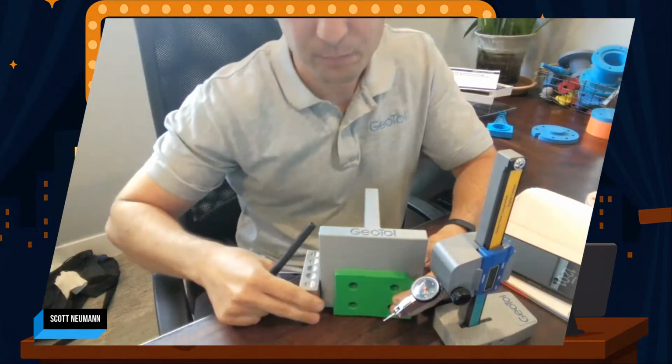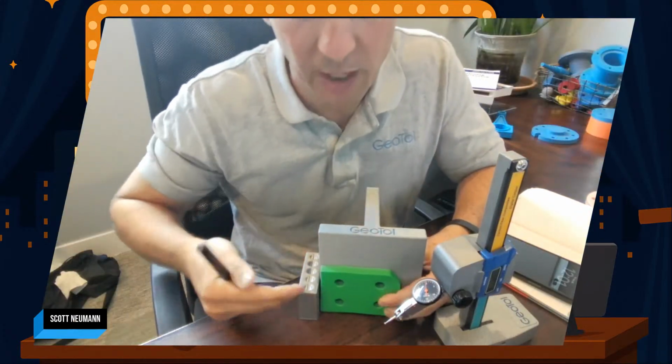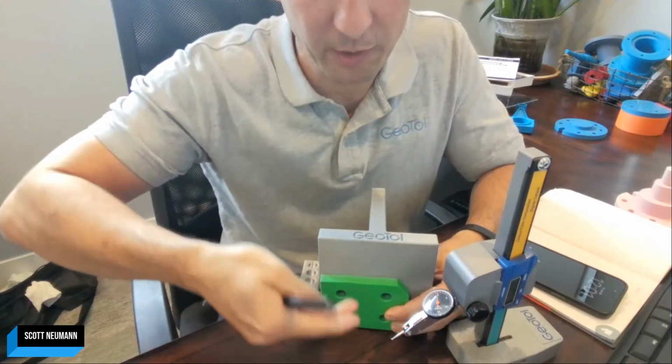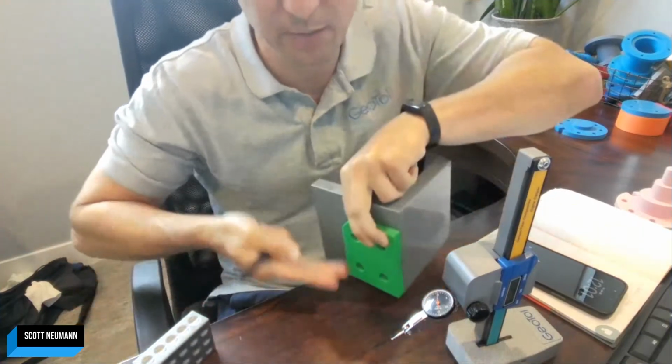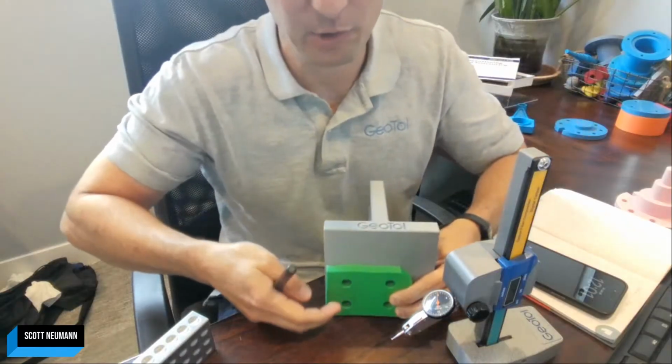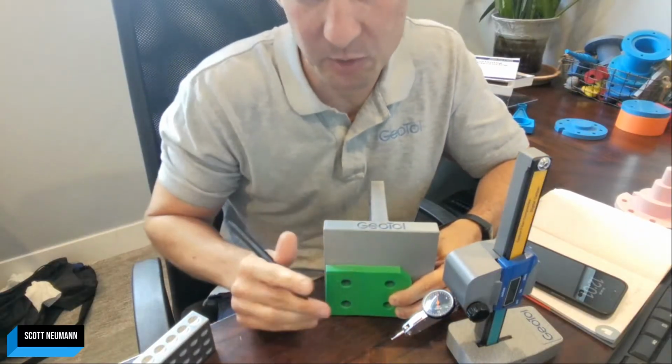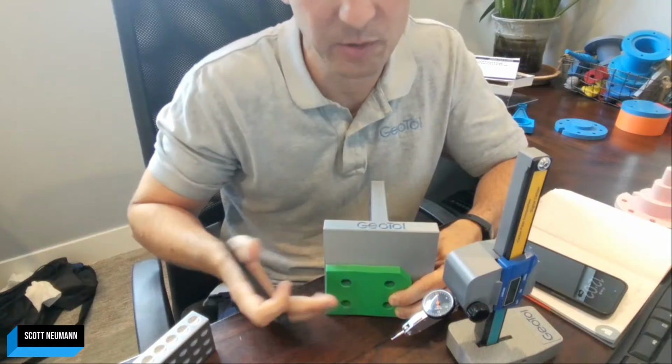Oh, you wouldn't need a CMM for something like this. This is such a simple geometry. This would be very easy, angle plate with a basic height gauge. So you'd set up the angle plate, set up A, set up B. You have probably a gauge block over here for setting up your C, and then measure the hole in the Y direction, rotate, measure in the X direction, and then make sure that combination of X, Y, like Custis was saying earlier with the Pythagorean theorem, it still lies within that tolerance zone.